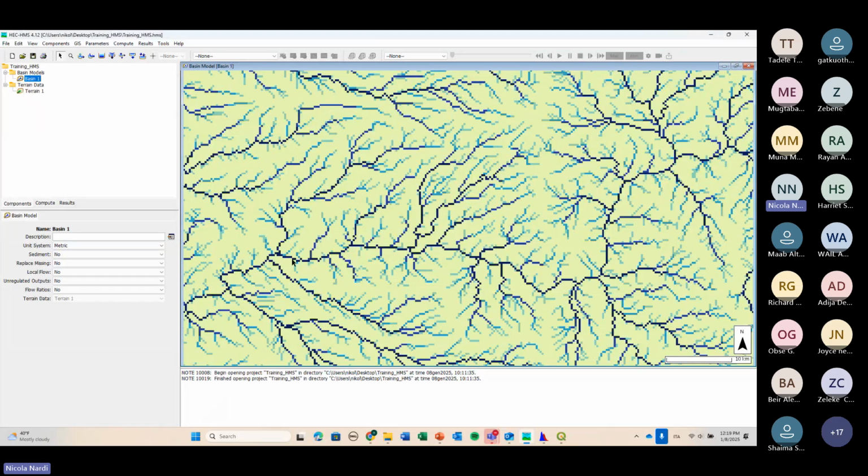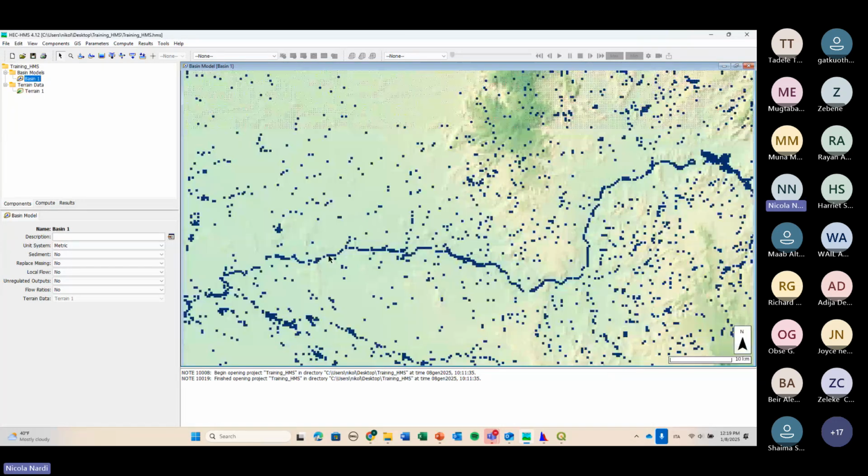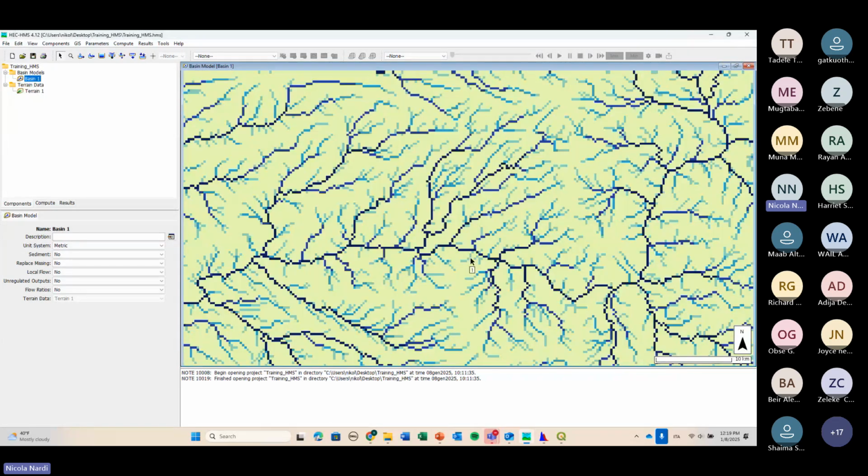The flow accumulation is the accumulation of all the locations that are upstream of my site. It's a bit tricky, but at the end of the day, what we are going to do is to use this raster layer to create the streamlines of our subbasin.